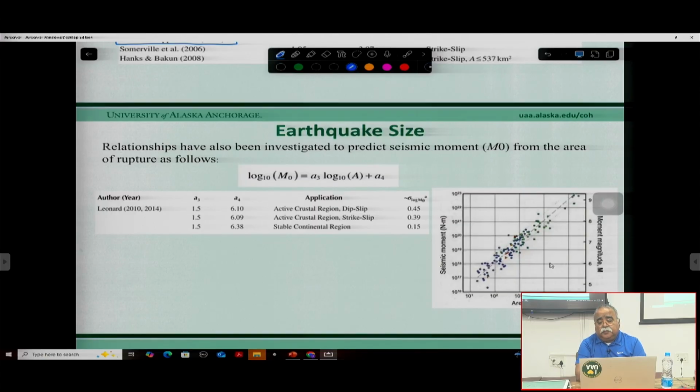So that you can calculate, and on the left hand side they have the seismic moment magnitude MW. So you can put this line on this side, then you can calculate the seismic moment. So for a given area, you calculate this one and find out the seismic moment release, and this will be the seismic moment in Newton meter calculations. Okay. Any question up to this much?